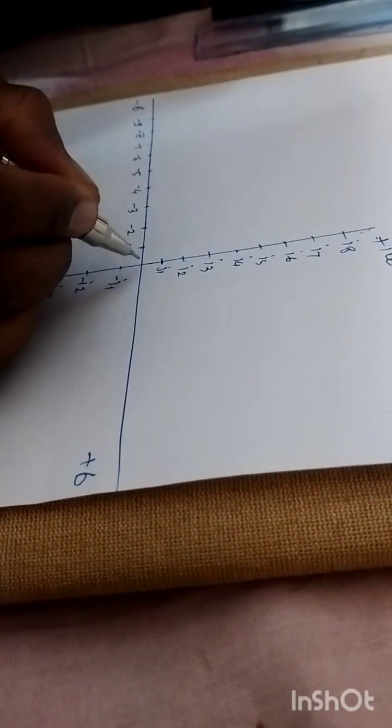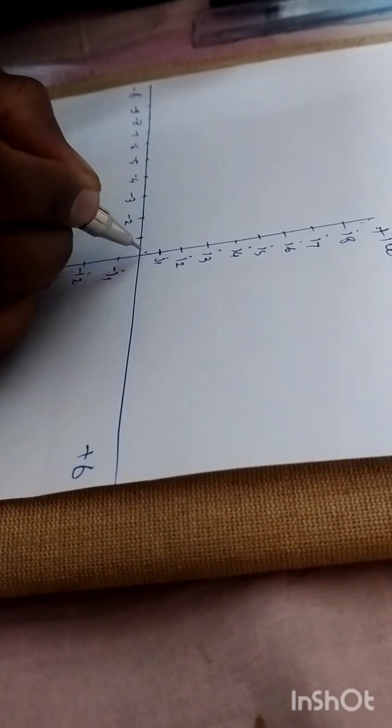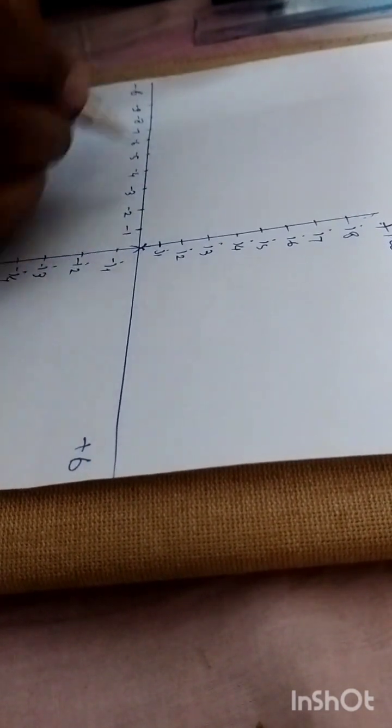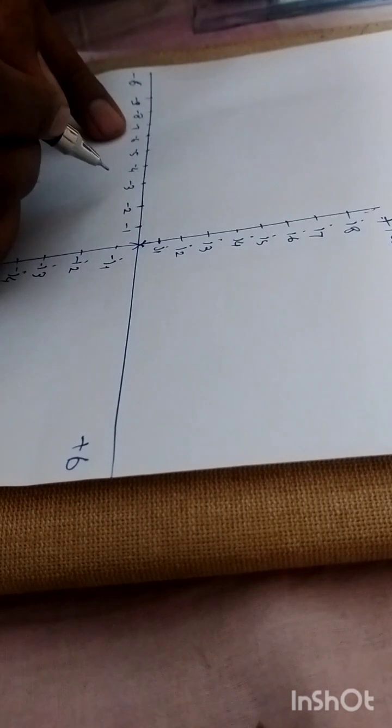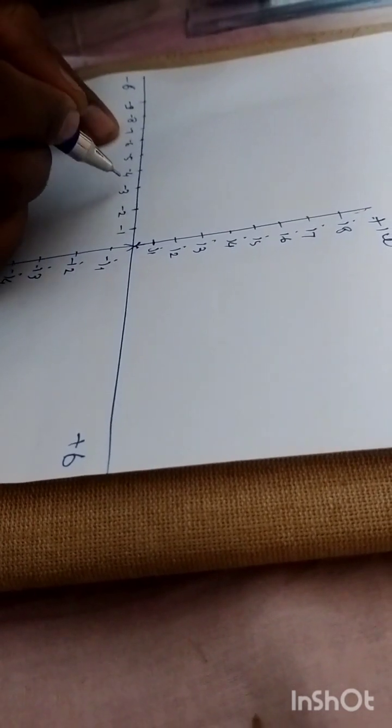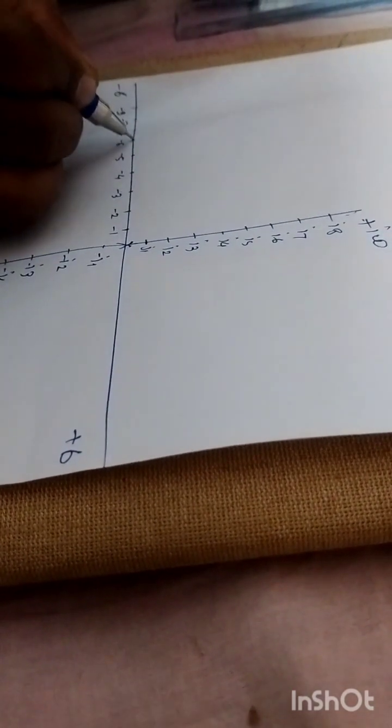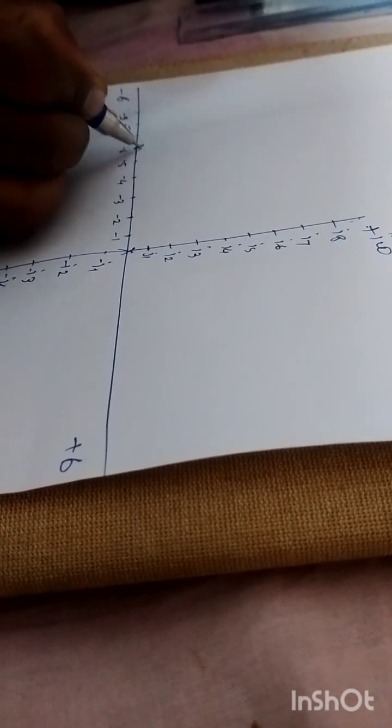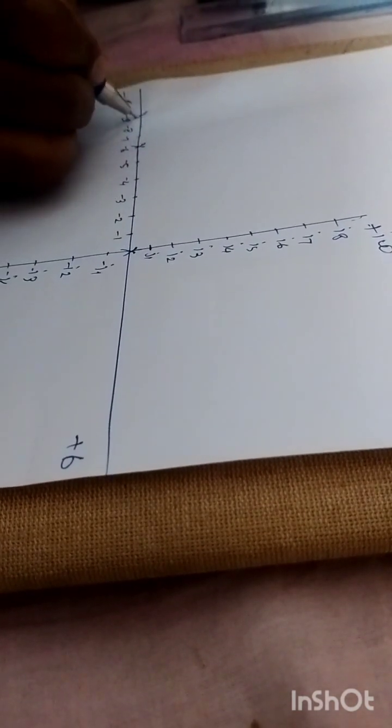So the first pole is located at the origin, that is nothing but 0, right? The second pole, according to our system equation, is located at minus 6, and the third pole is located at minus 9. We don't have any zero. If we had a zero, it would be denoted with the bubble sign, right?